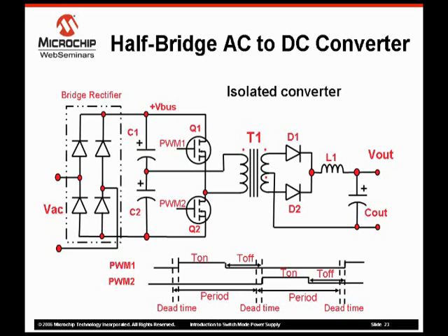If one transistor conducts more than the other, the voltage at the junction of C1 and C2 will shift up and down in a manner to equalize the current flow between the two transistors.